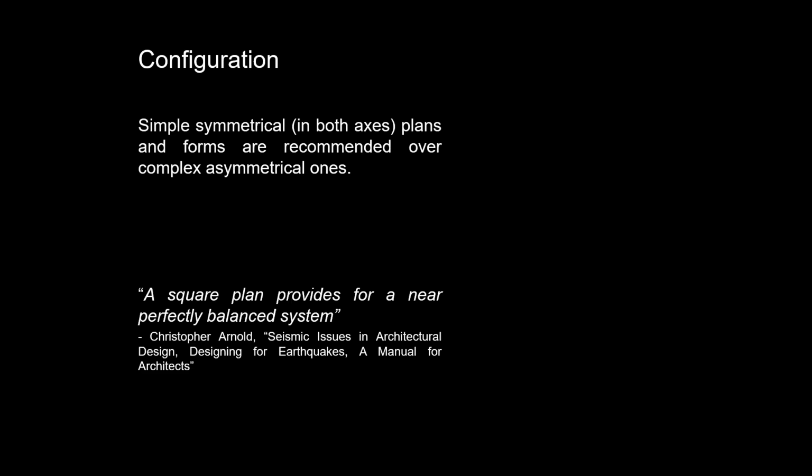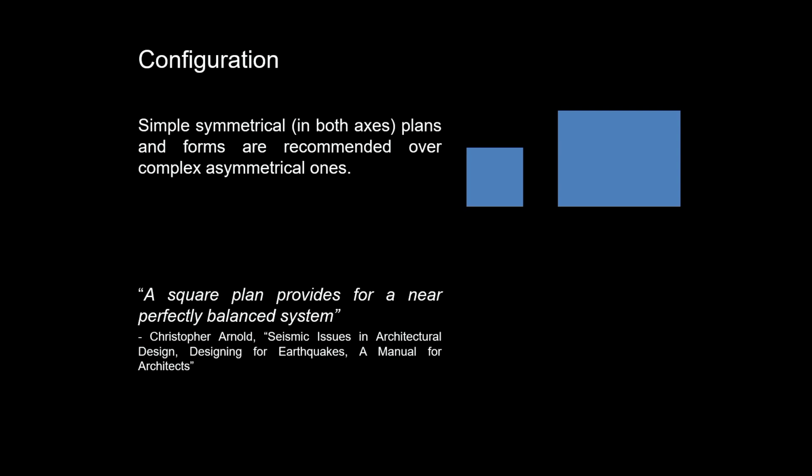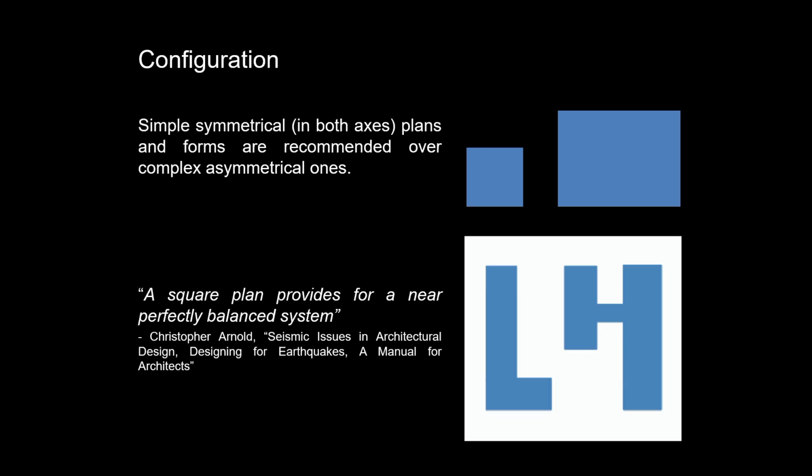From a seismic performance standpoint, simple forms and shapes, as Tony has repeated and said again, are recommended over complex ones. The top drawing, a square or a rectangle with proportions like 1 to 1, 1 to 1.5, are considered simple and preferable to the lower plans that are elongated, L-shaped, or H-shaped.